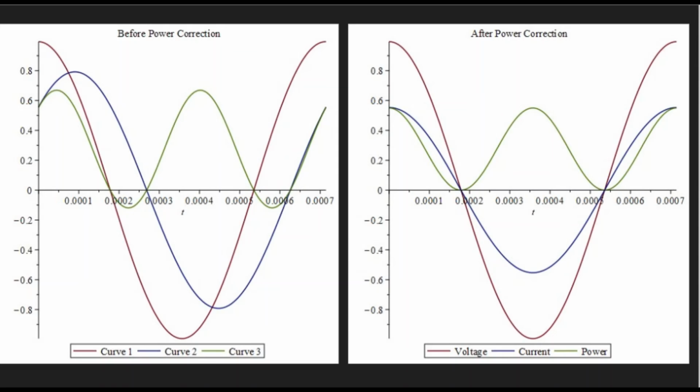The phases go to 0 after the power correction as the capacitor shifts the current signal the opposite way, canceling the inductor's effect. So the power factor is corrected to 1. The power correction is evident by the complex power becoming completely real after the capacitor is added, since the source is relieved from having to provide an out-of-phase current to the inductive load due to the capacitor being able to do this, thus eliminating net reactive power. This increases the efficiency of the circuit and is an application of cost effectiveness when it comes to electricity bills. These results are seen throughout all 3 methods.